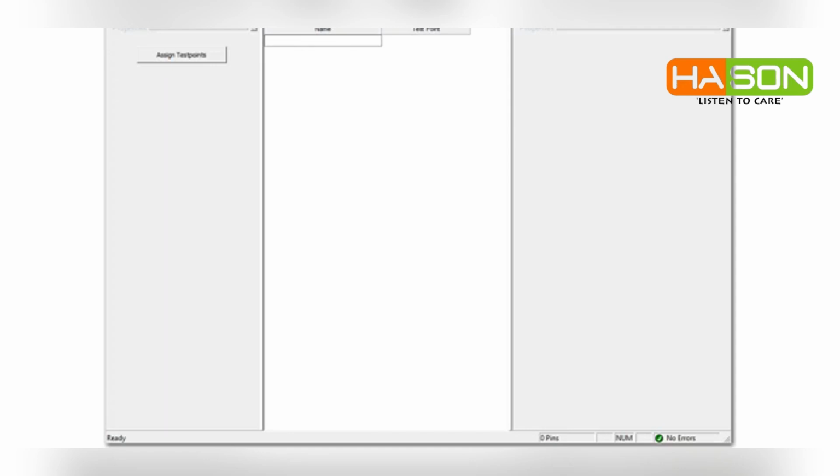After launching the NX editor, this is what you see. The NX editor provides several different views. Upon startup, you see the fixture blocks view. To go from one view to another, simply use the arrows on either side of the view indicator. The very first step in creating a program in the NX editor is to define the fixture blocks. So always start in the fixture blocks view.